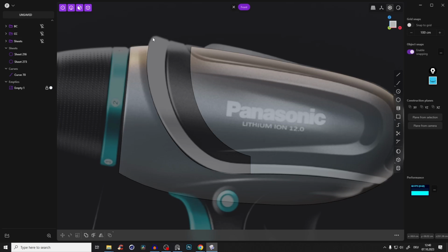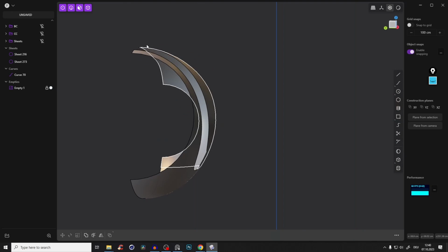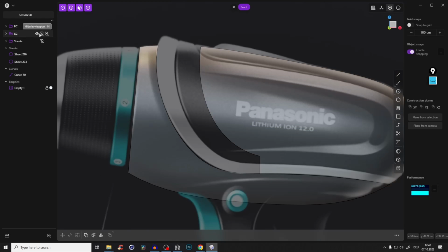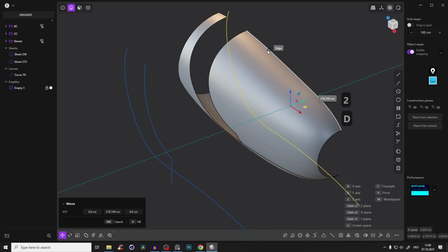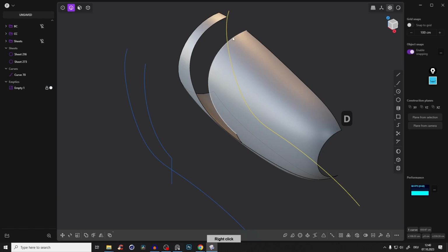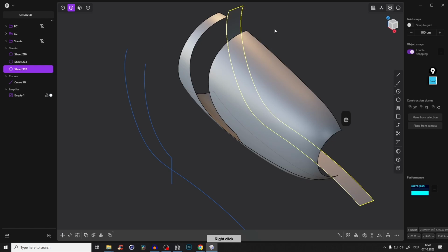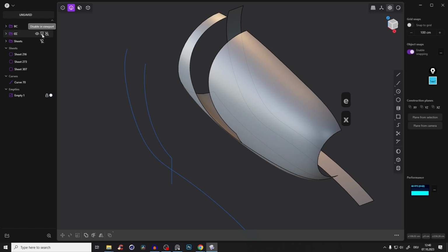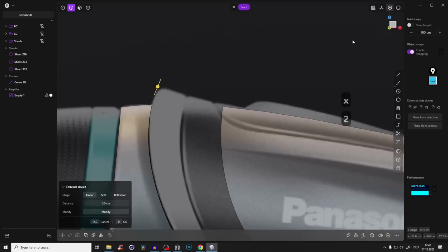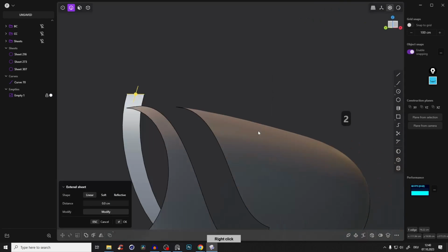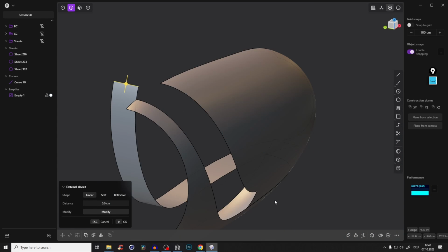So now we have to rebuild this whole shape, and also here from the front. So bring the cut curves back, and just for now, maybe you can even Shift D and bring it here to the middle. Right click, this is fine, and extrude it, because we will need an edge, and delete this curve and disable those ones. So we need this curve here, right? Because it's the same point, and we have to rebuild it.